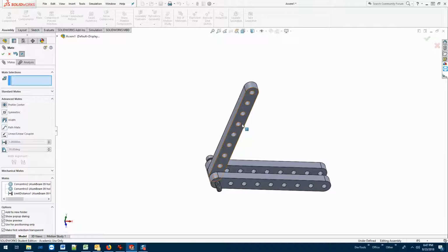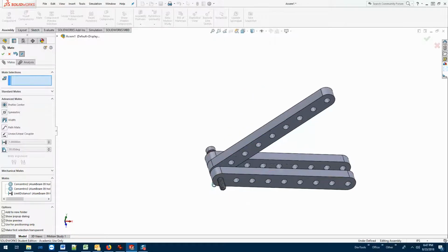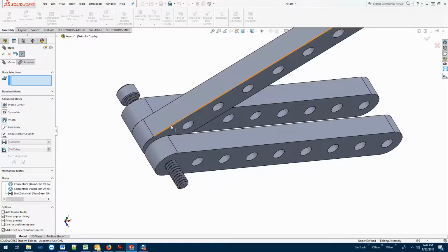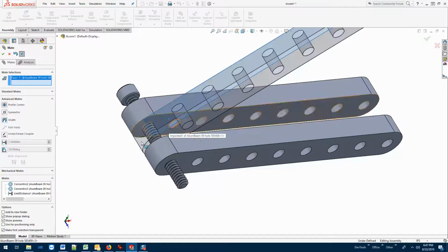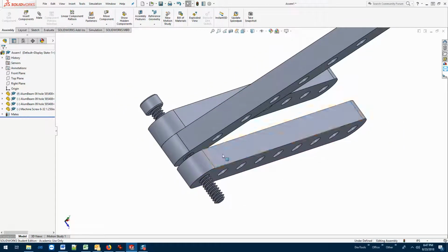Okay? Why, sir, did you choose 0.05? 0.05, because I knew from the math this is a 1/4 of an inch thick. The beam itself is a 1/4 of an inch thick, and I set the distance in between this beam and this beam at 0.3. So if I take 0.3 and subtract 0.25, a 1/4 of an inch, that equals 0.05. So okay.